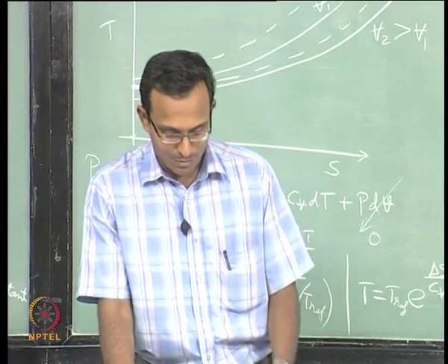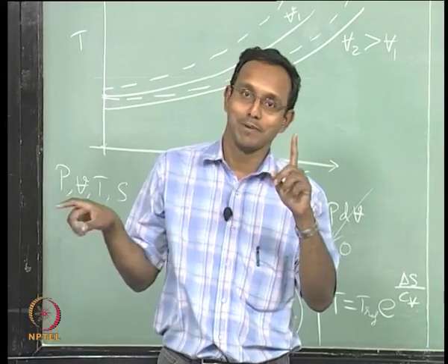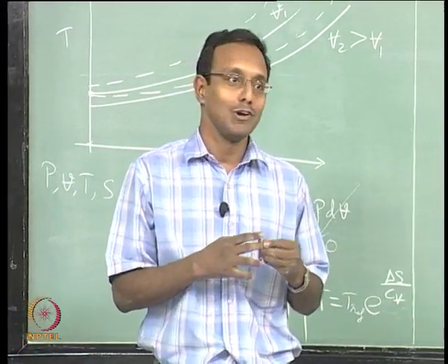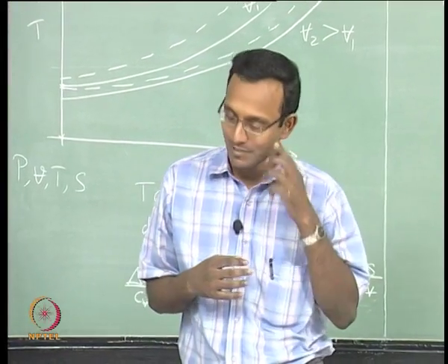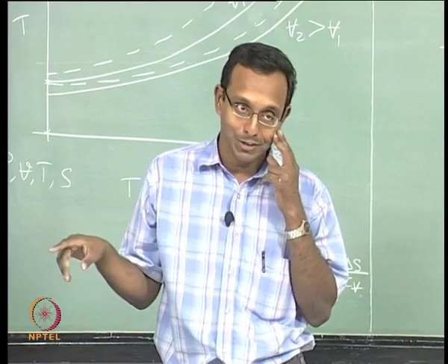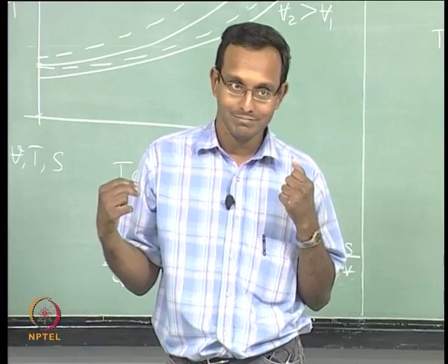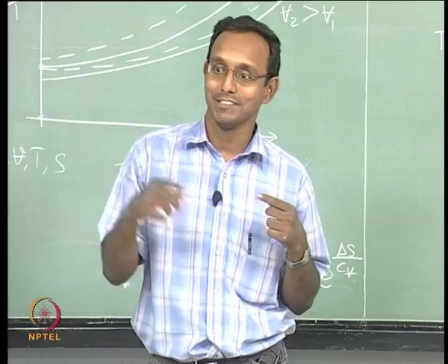More useful curve will be trying to plot pressure versus temperature axis, the remaining two constant curves, volume and entropy constant curves. Plot that also, it will be useful for you. Pressure versus temperature volume curve will look like what? Constant volume curve? Straight line, rising as temperature increases.